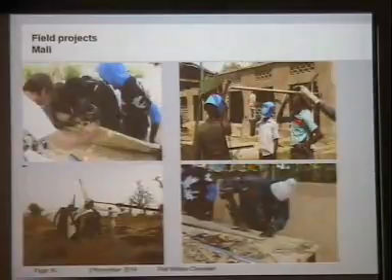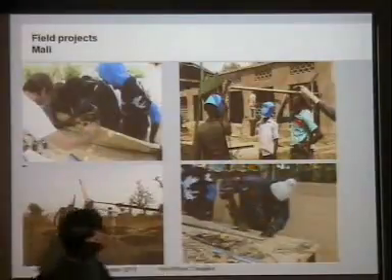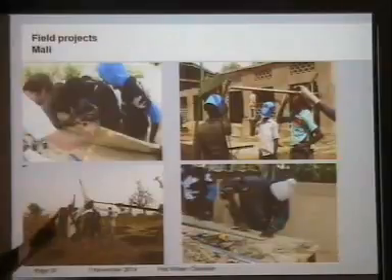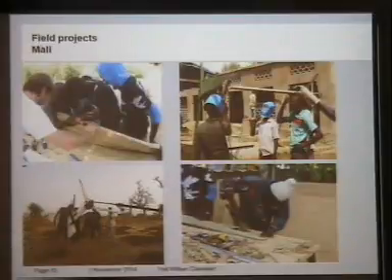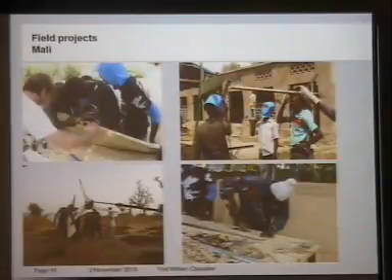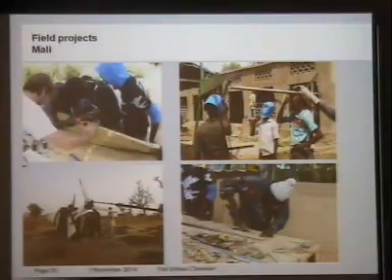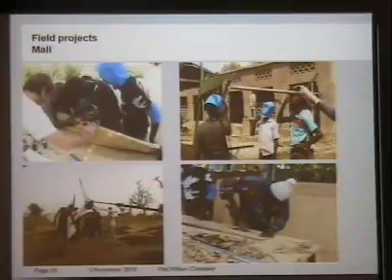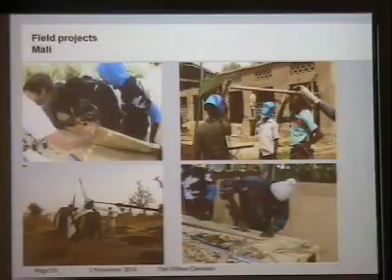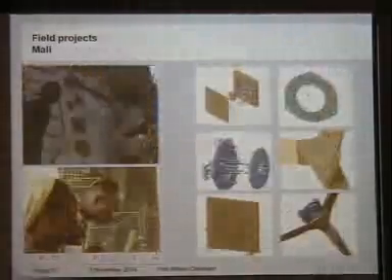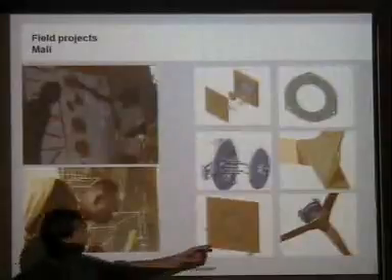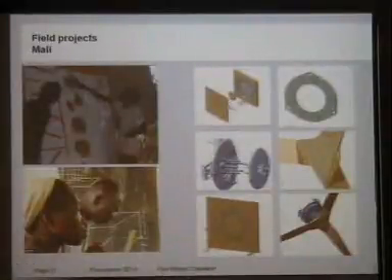Here you see them working. They like to work with their own tools. Maybe something nice to share: I learned this from Leila, from Solar Med, 4 years ago. We paint the tips blue. After a while, we can visually check from the ground if they start becoming white again. If they do, you know the tip is starting to erode and maybe I need to protect it. So with these little simple things, you can enhance the detectability, which I think is a very important design parameter for whether everything goes well or not. I made a special manual. I spent almost 1.5 years learning to make these drawings.